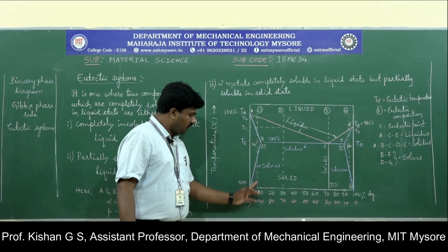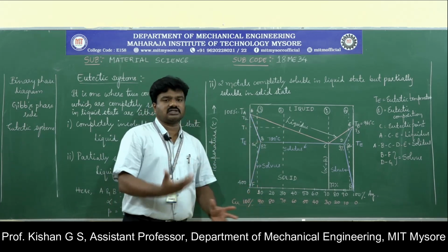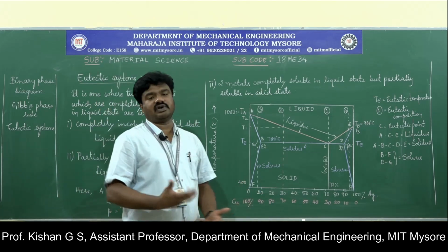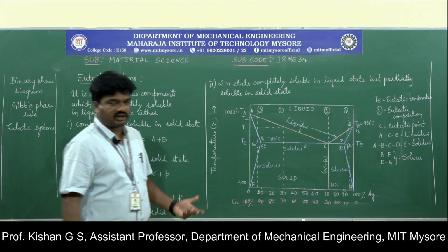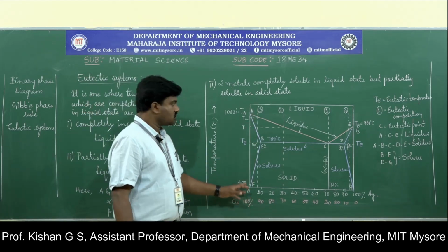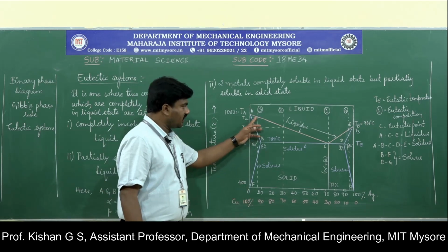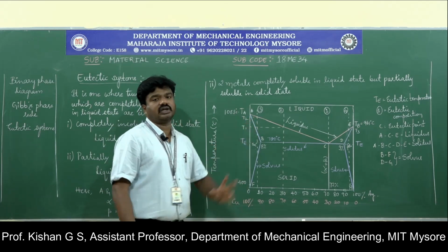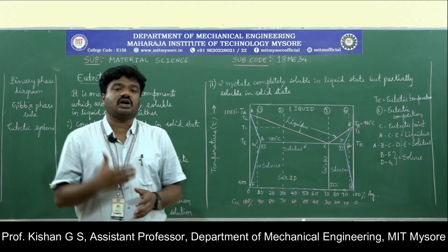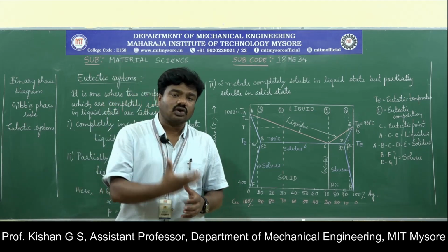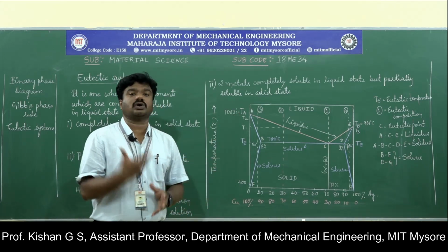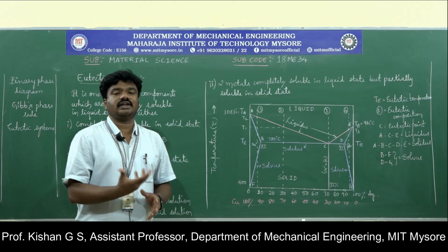With respect to the composition, for example, we have taken around 5% of silver and 95% of copper for the assessment here. So with 5% and 95% composition, what is happening? The corresponding temperature leads to T2 degrees Celsius. At T2 degrees Celsius the solidification of the copper material, that is material A in consideration here, is in progress, or it is initiated.